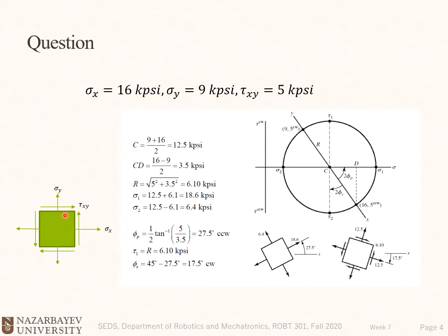So this is the applied coordinate system, okay? And we want to see at what angle we will have our principal coordinate systems. So in the past, we had examples of axial compression or tension stresses, or we had pure torsion. And in those examples, some of these elements were zero. But now we could see in this example, we have all the elements and none of them are zero, and see how we could deal with that, okay?